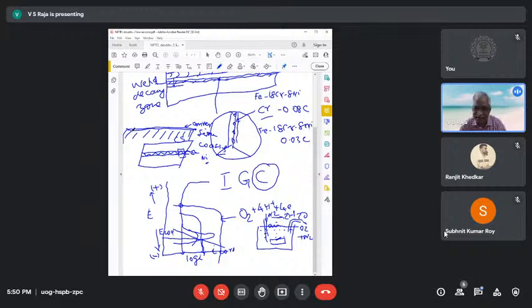This case is a coating formed by the corrosion process. Please look at it. It is not like stainless steel where you form a nice chromium oxide passive thin film. No, this is a corrosion product like iron phosphates, or sometimes you can change the phosphate into iron zinc phosphate, for example, or manganese phosphate.